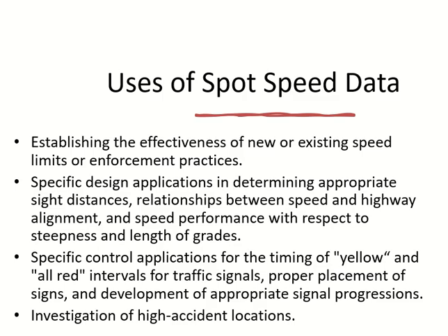In Bahrain, in Saudi, and maybe in Abu Dhabi as well, we analyzed the data. We found that among the most common reasons is overspeeding. Bahrain, I'm sure about it. Saudi, the data which I have seen for a few cities, I'm sure about it. Abu Dhabi, I'm not sure, but overspeeding is one of the most common reasons, maybe in the top 3 in all the cases. So you would know about it when you do the spot speed study at that location. You know the drivers are overspeeding. Without that you cannot know.